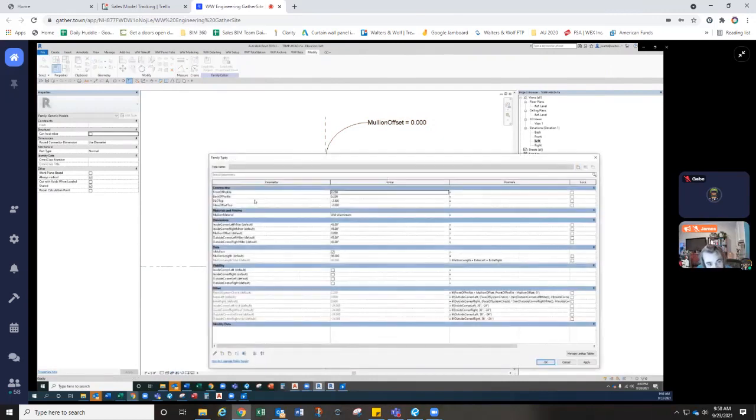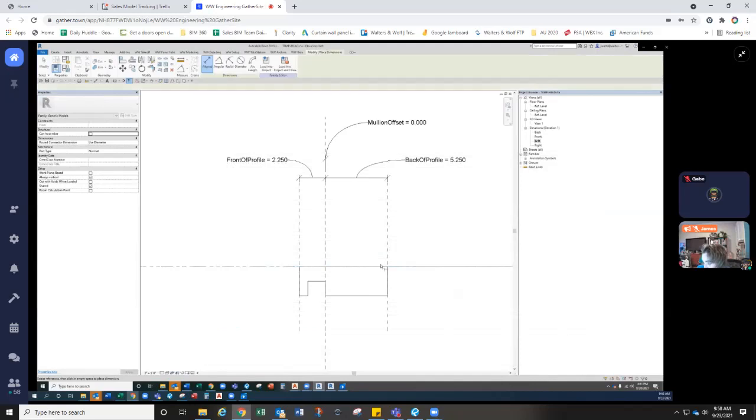We have the parameter DLO top, which helps us set where we want the shadow boxes and back pans to go up to. Right now it's set, as you can see, to -2.5. And if we take a measurement from here to here, you can see it's 2.5.